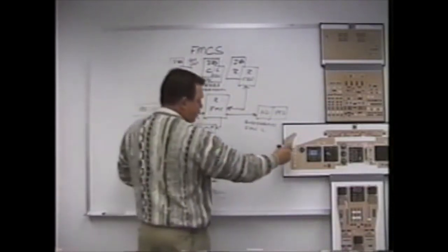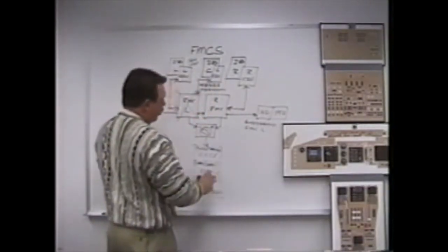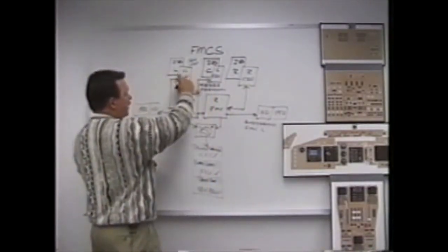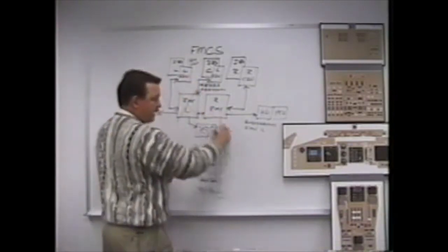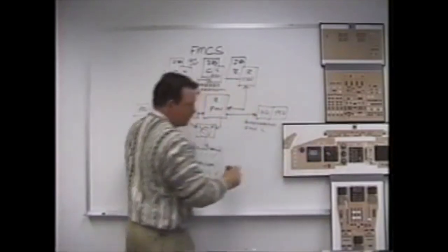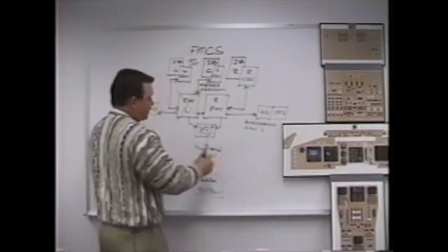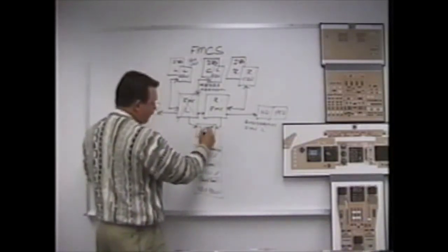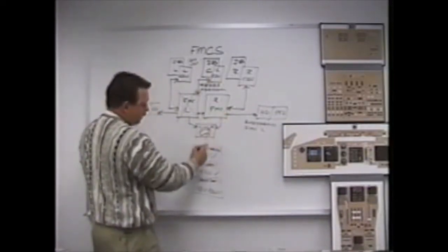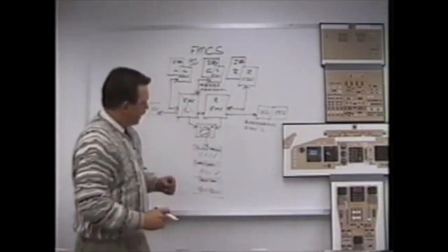The first procedure will have us move the switch to the right FMC for the captain's display. What that will do is rewire the CDU, the PFD and ND over to the right FMC. As a result, the captain can get all of the information displayed back that the left FMC took away. The second switch we're going to move is this selector switch here. The procedure will have us move this to the right. When we do that, we regain our signal flow to our auto throttles, to our LNAV and VNAV, and our auto tuning of the nav radios.